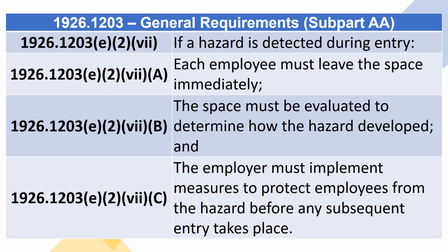1926.1203(e)(2)(vii), if a hazard is detected during entry, 1926.1203(e)(2)(vii)(A) through (C), each employee must leave the space immediately. The space must be evaluated to determine how the hazard developed, and the employer must implement measures to protect employees from the hazard before any subsequent entry takes place.